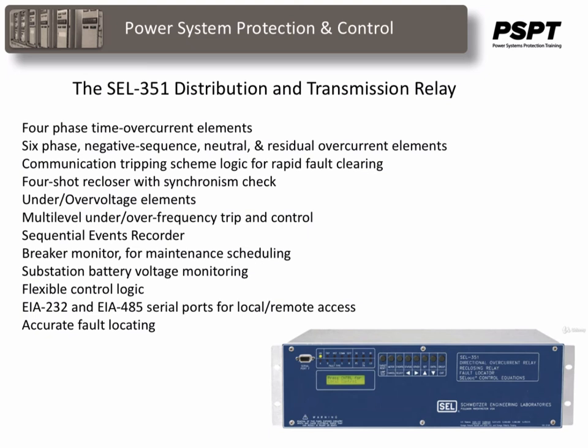Now, modern relays tend to talk to each other, and that's what these communication ports will do, and it gives you a whole lot more flexibility for protecting your station and your feeder lines. It also has an accurate fault locating system for quick circuit restoration and increase of serviceability. In other words, it will point out where the fault is so that the line crew could get to it more quickly and do the repairs.